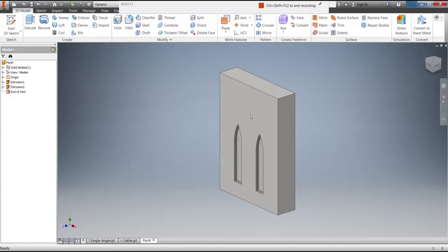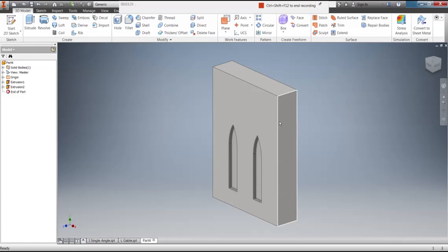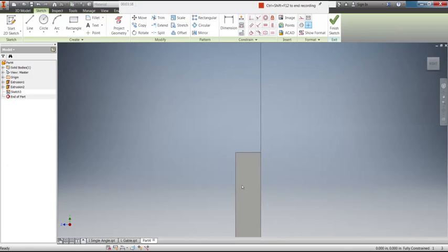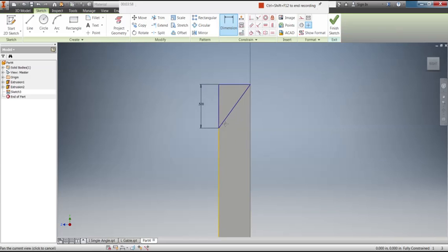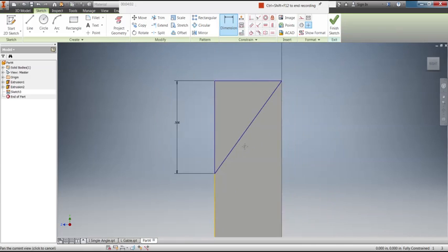Alright, now I can make the slanted top for the angle piece, and then I can come back and do the gable for the other one. So for the slanted top, the slant comes down 1/2 inch. So I'm going to make a sketch on this side, and I'm going to create a triangle. This triangle is going to represent what I'm going to cut away. So I'm going to do 3 sides to it here, and then I'm going to set the distance on this side to be 1/2 inch. And I will go ahead and add the grooves that I want to add right away as well. The grooves are about 1/16 inch thick, and there's about 1/8 inch between the top ones and a little bit less on the bottom.